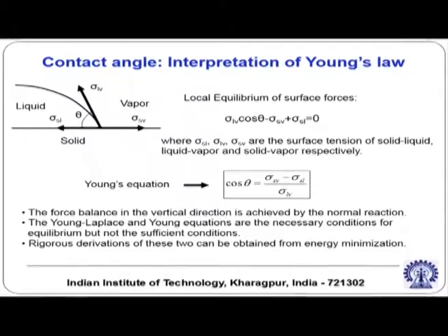What about the vertical force balance? Nowhere is it discussed. So, if the vertical forces are not balanced, there is an unbalanced force, and the droplet might suddenly start accelerating in the vertical direction. We never see that happen in experimental practice. That means something intuitively takes care of the vertical force balance. This is not a true free body diagram because this shows an unbalanced vertical force.